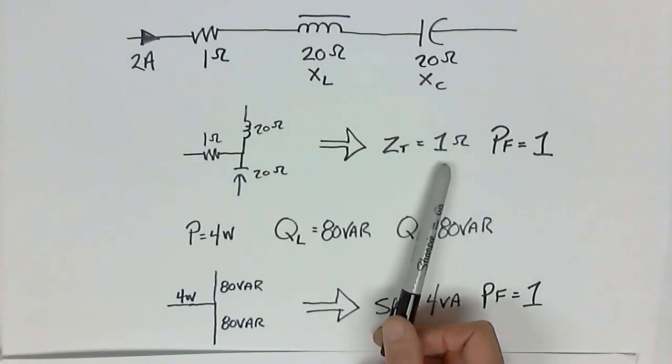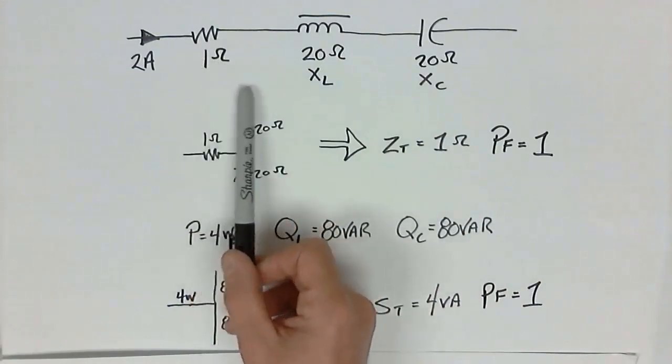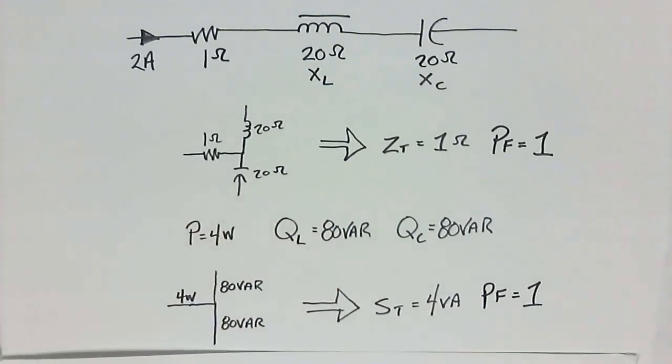What if the resistor was only 0.0001 of an ohm, as in a conductor? What would happen to the total current if it was only 0.0001? Wouldn't the current be really high? And it would. It would be a bad situation. And at times within design of larger systems, the conductors themselves pose a little bit of resistance. They are also typically coupled capacitively to ground, which is not really an intention, but an outcome of using AC. And due to the electromagnetic flux, they do possess a certain amount of inductance. So it's an interesting scenario.